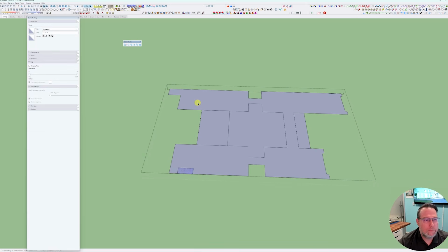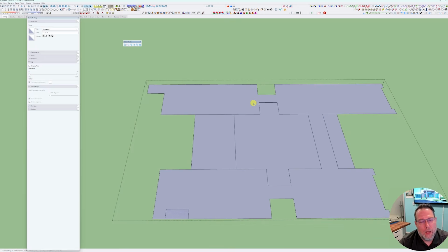So how do we put all the pieces we've talked about together into one system of workflow using all of the clean commands, the solid inspectors, and the solid tools? Well, I'm going to first select what I'm calling the interior, or the shell of the house. I'm going to double click that because, again, we talked about selections.